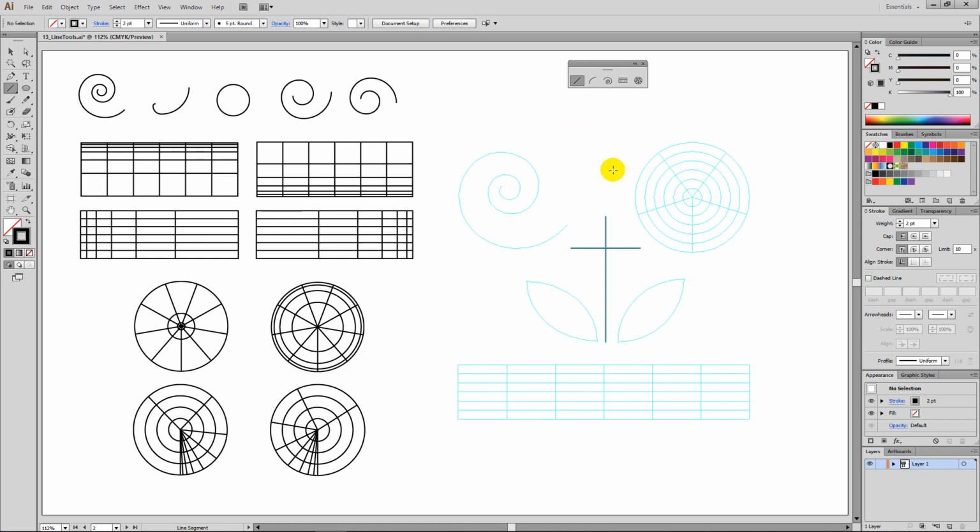With the Line Segment tool selected, click the Artboard. In the Line Segment Tool Options dialog box, type length 5.5 cm, angle 45 degrees, and then click OK. If you want to draw lines with the desired length and angle, use the dialog box.